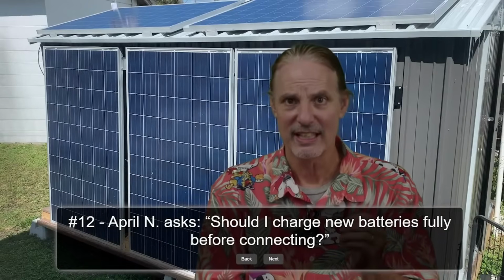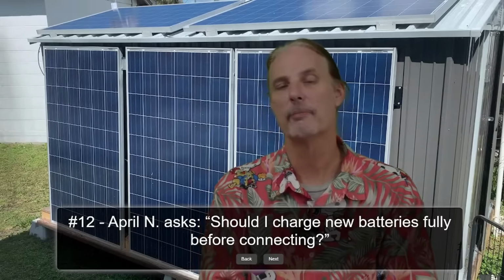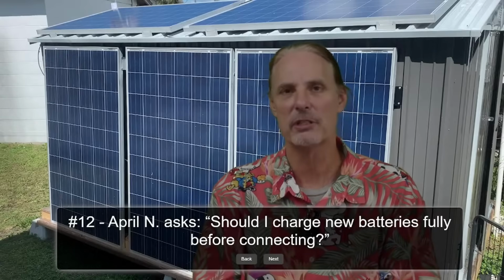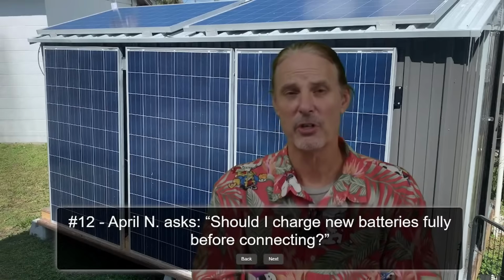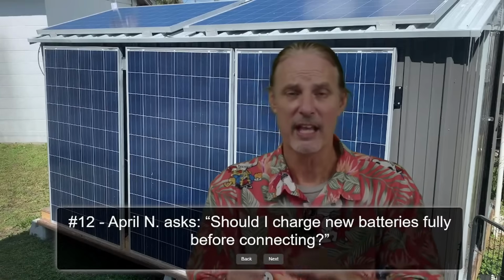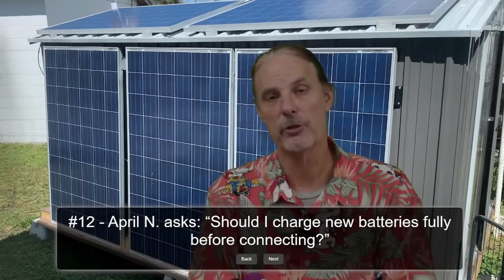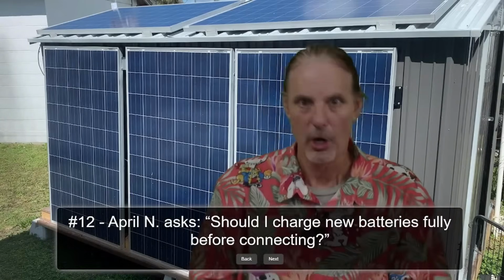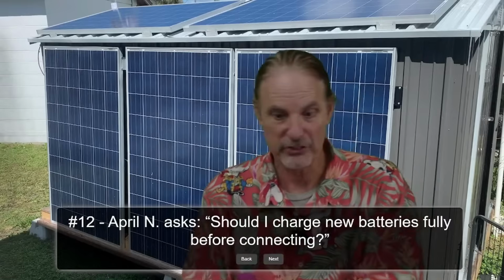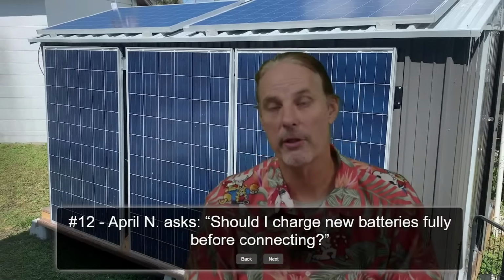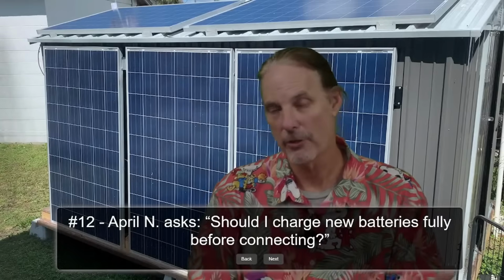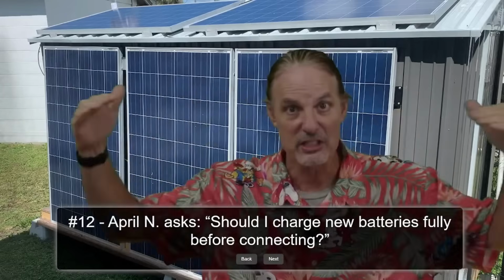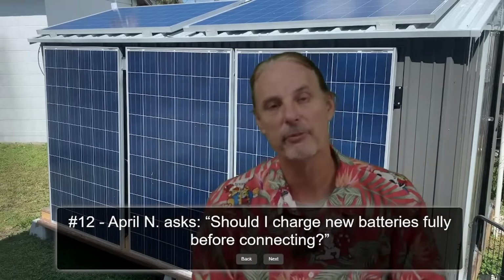But this is exactly why they do it, because charging all of your batteries up to full and then turning it on is a very easy way to solve any problems you might have, especially if you're not familiar with meters, or you're inexperienced, or you're running in closed loop or something like that. You would want to just charge everything all the way up and then turn them on, and then you won't have any of these problems whatsoever. But if all of your batteries are all sitting at exactly 52.65 volts, then you could also turn them all on, and you wouldn't have a problem either. Nothing would transfer. The nominal difference between battery A and battery B and battery C and battery D needs to be as close to zero as possible, and that would prevent the transfer.